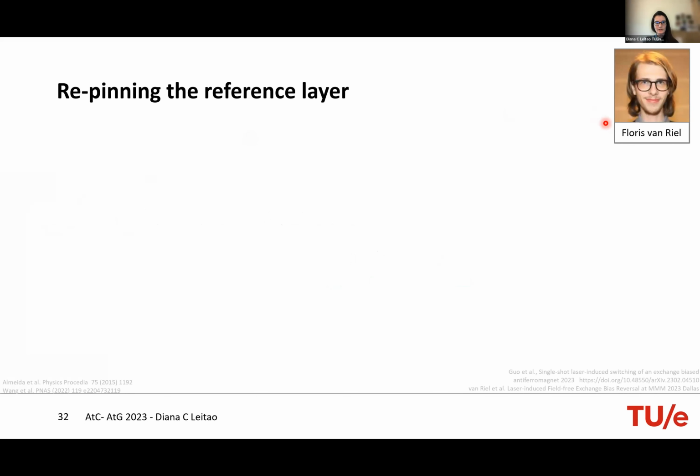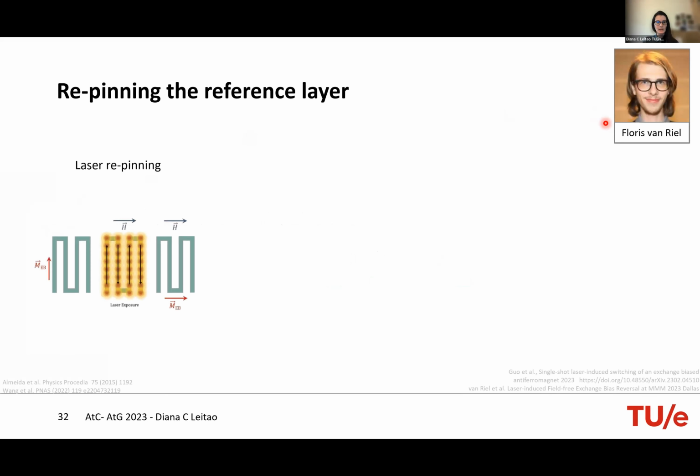And Floris has started with this quite exploratory topic and the question: can we take some inspiration from the laser repinning strategy that is used nowadays to locally define different orientations in Wheatstone bridges just by shooting a laser pulse, heating and then cooling under a magnetic field, similar to magnetic annealing?